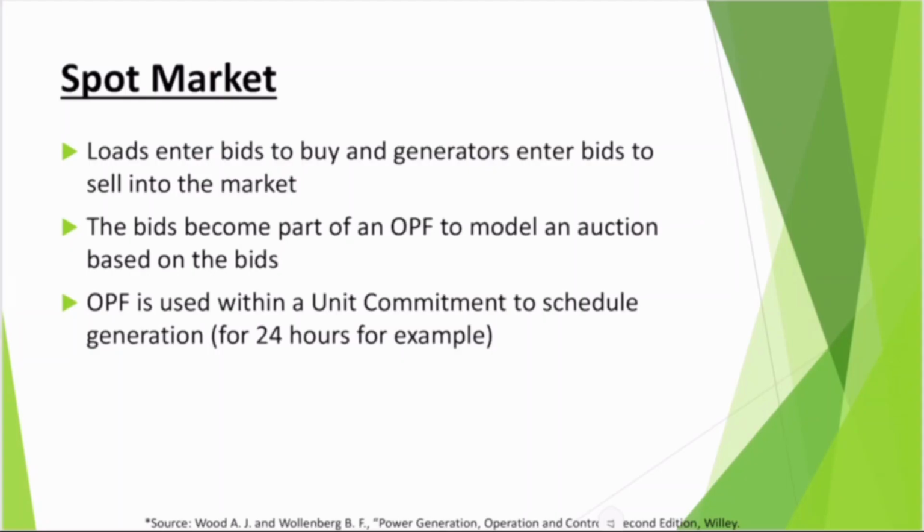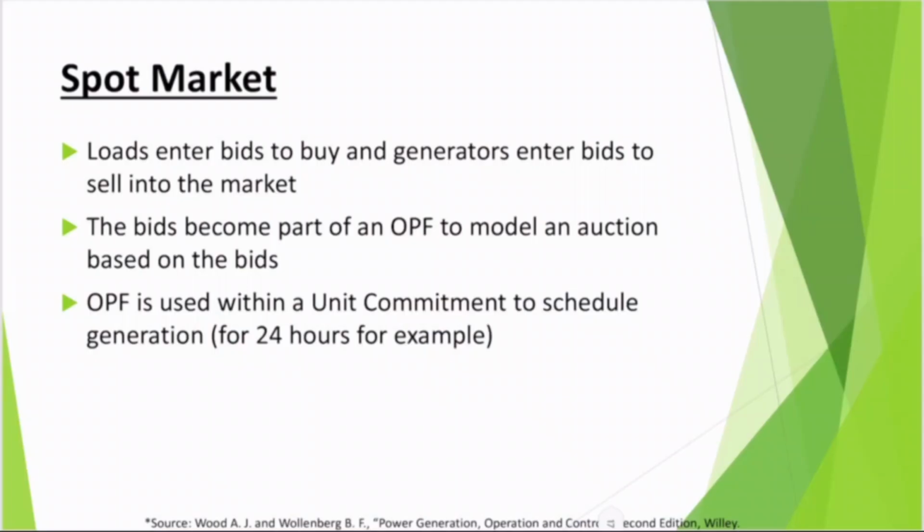Now, one more important factor is known as spot market. Loads enter bids to buy and generators enter bids to sell. It's the market. The bids become part of an OPF to model an auction based on bids. Now, OPF is used within a unit commitment to schedule generation for 24 hours, for example.